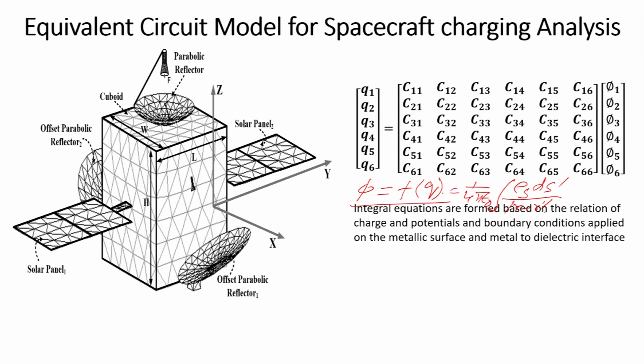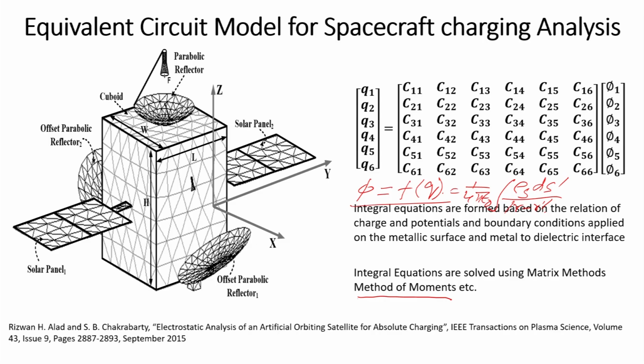You can consider here the dielectric or the material properties, everything you can use in this integral equation method, and you apply the boundary conditions. Then those equations can be solved by a matrix method known as the method of moments. So, this has been solved by the method of moments, and this is the reference, this work is there in this paper.